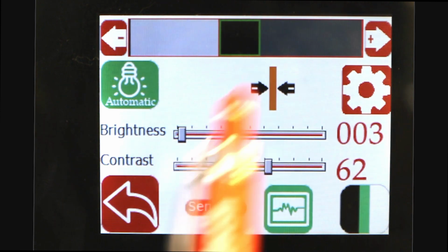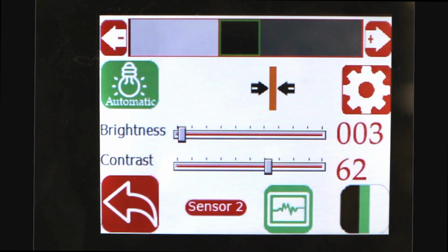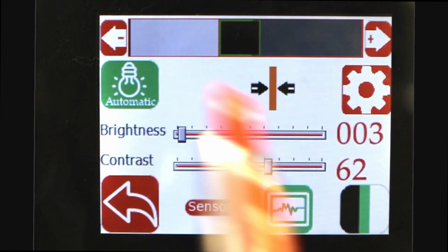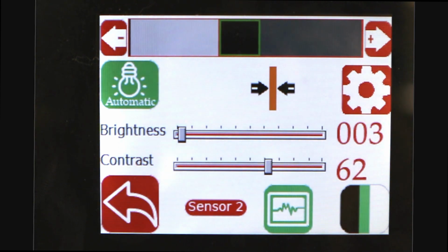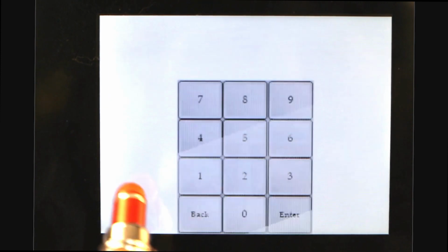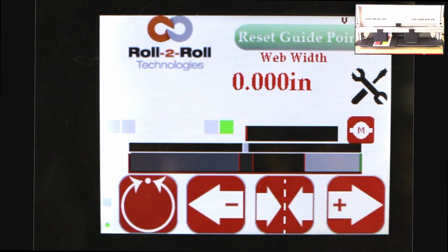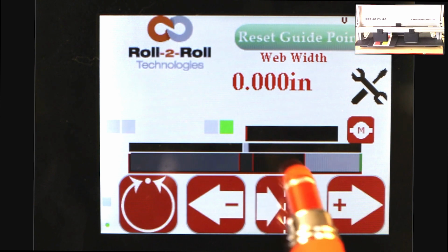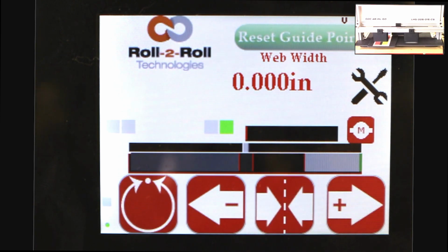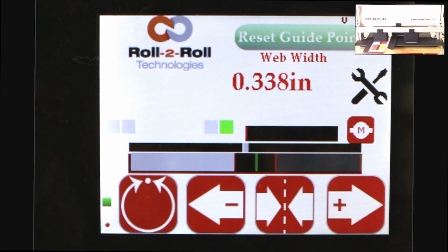And this is intended to make sure that we don't jump from one contrast to another. If you are measuring the width with this particular feature, then whenever the width changes too much or the color changes too much, you're going to have no measurement. What I mean by that is if I go in here and pick the next line, this is still a black line, but you can see that the width went to 0, even though there is a black line that you see here, and that's because it lost that contrast. Measuring the width of the web based on this contrasting feature is restrictive in line mode.